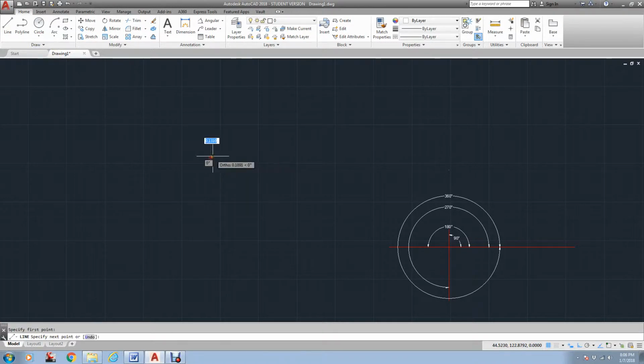I'm going to just select here, and as you can see I've got my ortho on, which if you haven't watched that video you need to watch it for ortho. I'm going to hit F8 and that frees it up. But if ortho is on, all I need to do to either go straight up and down or left and right is just type in a distance. Let's just say 10, and there I hit escape and I'm done. I've drawn a line 10 units long.